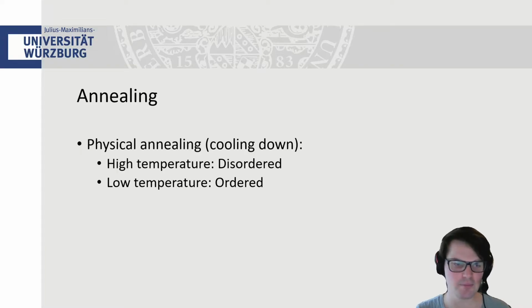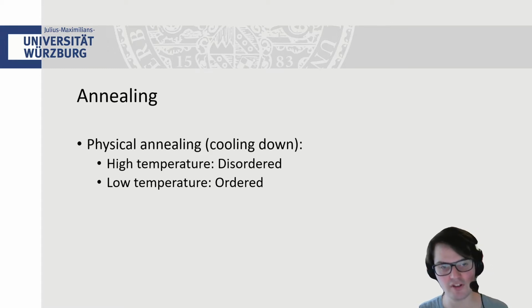When the metal is at high temperature, atoms can overcome the forces holding them in place. Thus, the atoms can move. By glowing, metal releases its energy and molecules slow down their movement. When this is done slowly, the atoms end up forming crystal structures. The results differ depending on the time taken for cooling down. Cooling down fast leads to less optimal states, but cooling down slow forms near perfectly ordered structures. By doing this, different properties of the metal can be achieved.